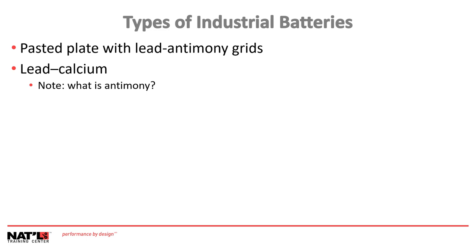For some time, China has been the largest producer of antimony and its compounds, with most production coming from the Hunan province mine. The industrial methods to produce antimony are roasting and subsequent carbothermal reduction or direct reduction of stibnite with iron. The largest applications for metal antimony are as an alloy material for lead and tin and for lead antimony plates in lead acid batteries.